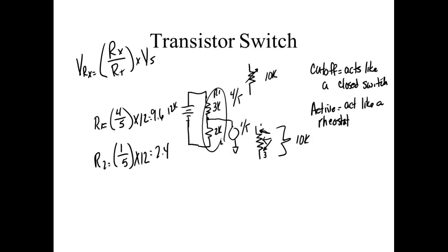We run into a situation in solid state where we're trying to set up an input signal, and they say that we need to put 1 volt in to get 10 millivolts out, and they set up a fixed voltage divider to get 10 millivolts out. Our generators won't put out exactly 1 volt, and every one of them puts out something a little different. So if we use a fixed voltage divider, we'd never get 10 millivolts. So what do we use? We use a pot. And now it's up to me to decide. Now I can put my meter on the output, right, you understand, and I can get the exact voltage I need.